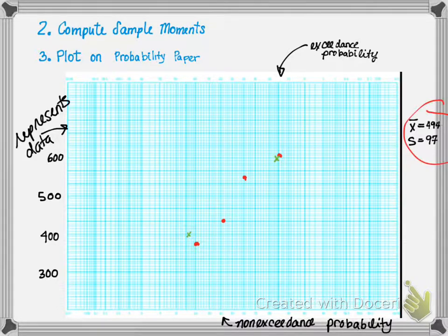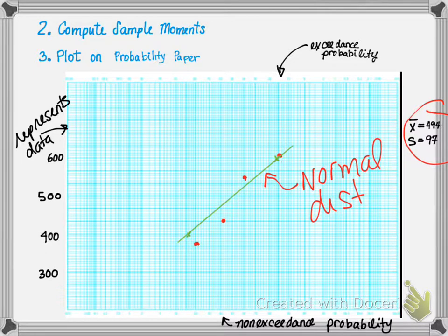I then, for a standard deviation of 1, you have a non-exceedance probability of 84%, and for a negative 1, you have a non-exceedance probability of 16%. So I put x's at those two, and I make a linear distribution. This is my normal distribution. We'll talk about this more in detail in class to make this concept really clear. This should just be a quick review or an introduction with further clarification occurring during class.